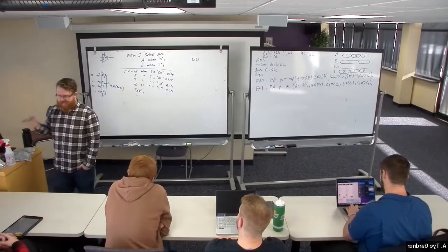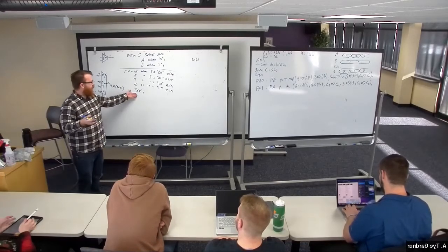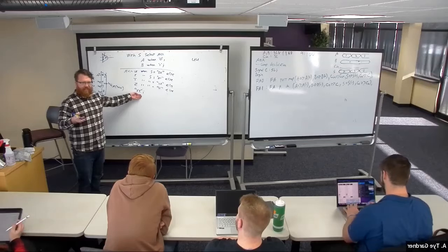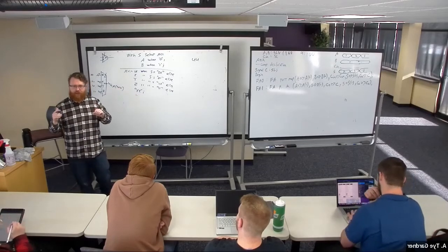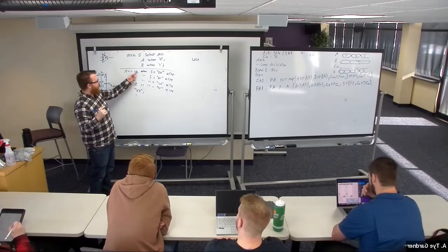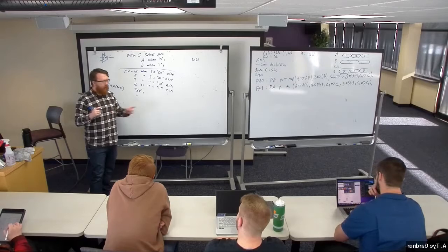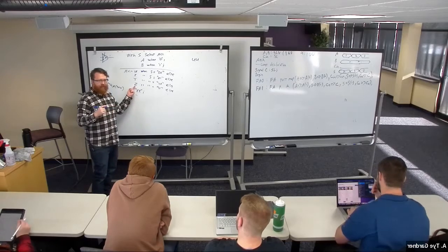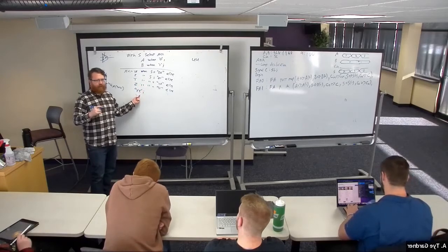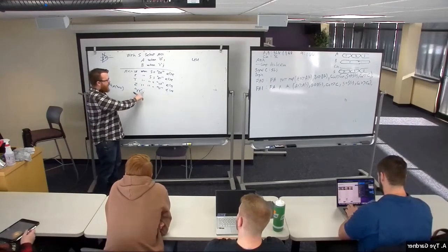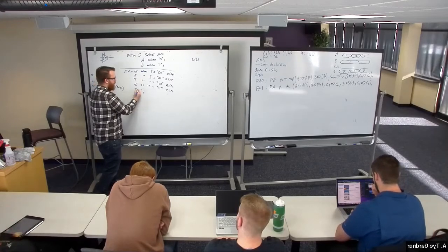So maybe, right, X's are allowed. Now, if I put select as anything that isn't a useful number, my output of mux is going to be X's. And that's a useful debugging tool because now when I look at the waveform, I go, oh, something must be wrong with my select signal. Otherwise, I could fall into this trap of what is it actually doing, whereas this can be helpful. Anything that you put here is actually really helpful.